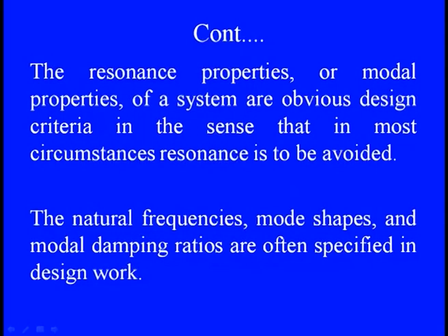So this was the second factor, and the third is resonance. The resonance properties or modal properties of the system come under the design criteria, in the sense that in most circumstances resonance is to be avoided, whether it is resonance of the entire system or within the material.